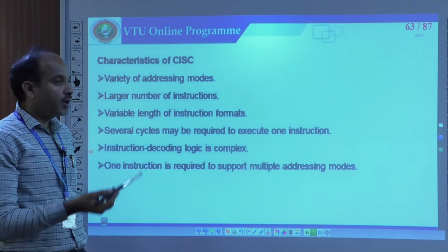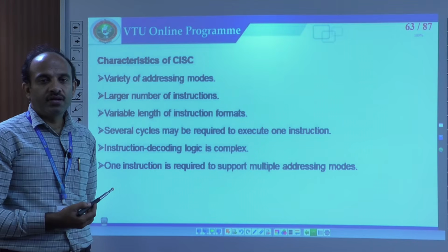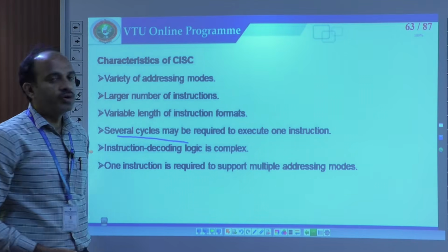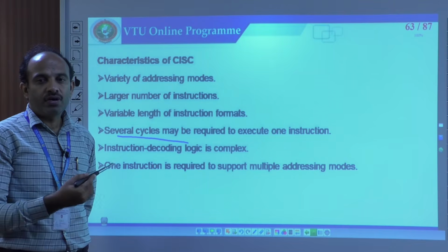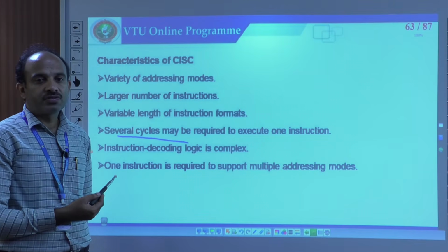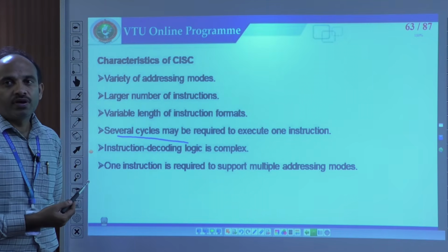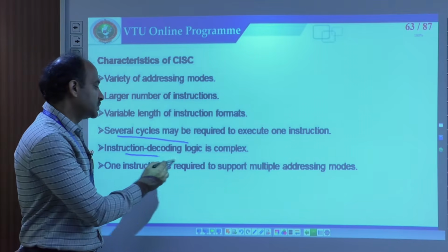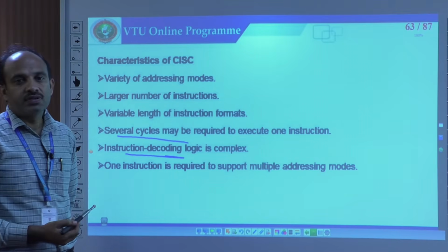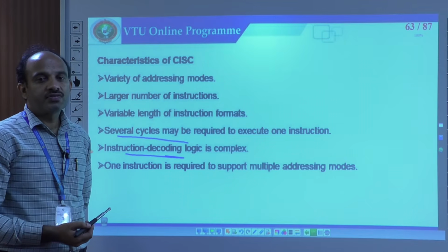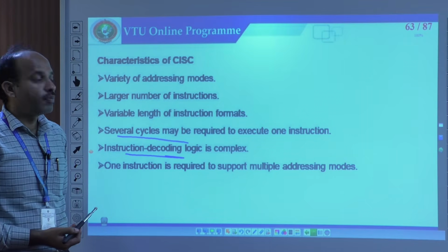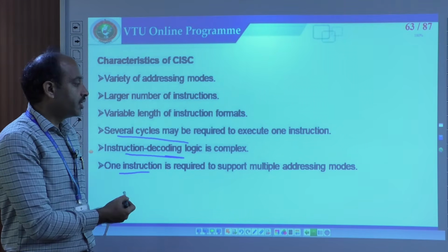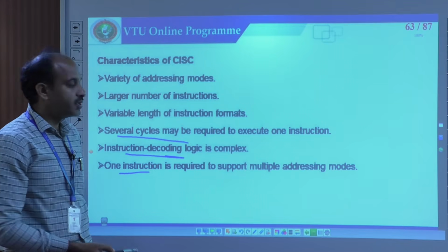In RISC there is one cycle execution time, but here several cycles may be required to execute one instruction. And instruction decoding is the complex part in this CISC, and one instruction is required to support multiple addressing modes.